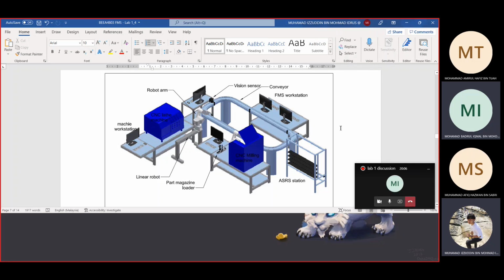The part on the milling table of the CNC Milling Center is fastened using a specially designed pneumatic clamp for further processing. Next, the material handling unit is pneumatic powered and is used to transfer the parts between the conveyor and the CNC milling center. The arm robot at the milling station will put the machined part on top of the jig.